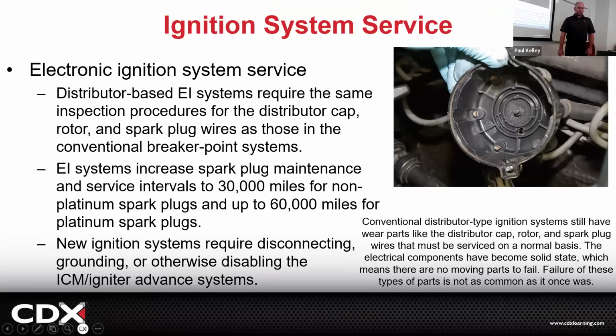And then we'll get into how it was, how we test it, and how it is now. So if it was a distributor type system, this is the underside of your distributor cap. We had these little contact points. You guys remember that from last week, how we saw the distributor spin? These would get corrosion, these would get arcing. I've got a picture of carbon tracking, right? And this little center one, that's where the high voltage comes from the coil. That one is spring loaded, and it would wear because it's pressing on the spinning rotor. There's moving, spinning stuff, and it would just wear out.